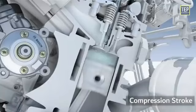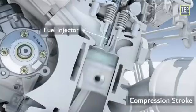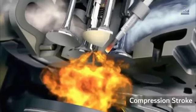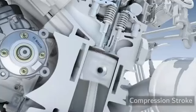Just before the piston reaches top dead center, diesel fuel is sprayed inside the cylinder. The fuel is sprayed by means of a fuel injector at a very high pressure, overcoming the pressure of the compressed air. The fuel gets mixed up with air, which contains oxygen. Since the fuel is a hydrocarbon, the temperature of the compressed air is sufficient to initiate the combustion, and the fuel is burnt.